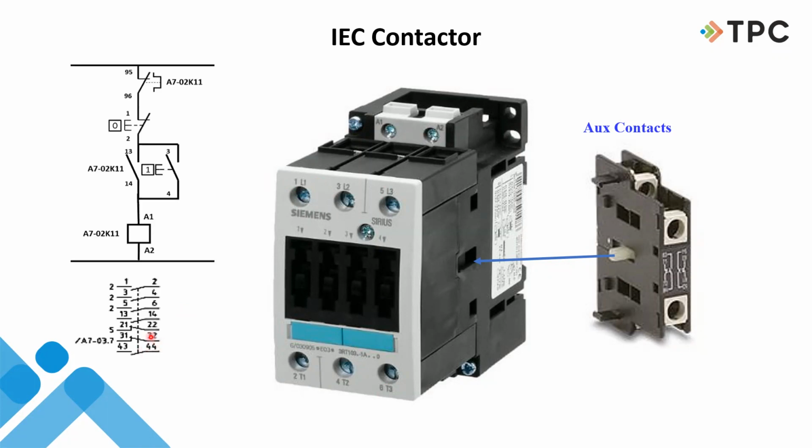And this is one I told a member: if there's a number over here, it'll tell you. So this set of contacts right here, this 31 and 32, are being used in group A7 on page 3 on rung 7. So it takes me right to it. Makes it easy to go there.